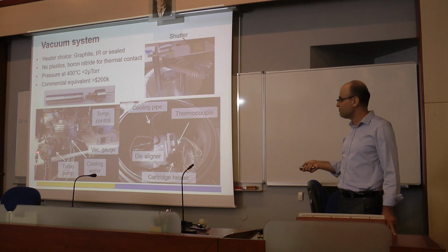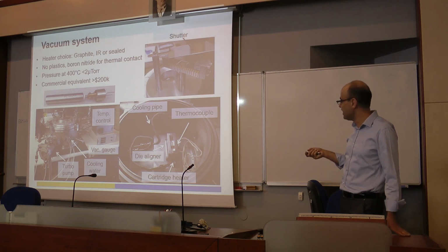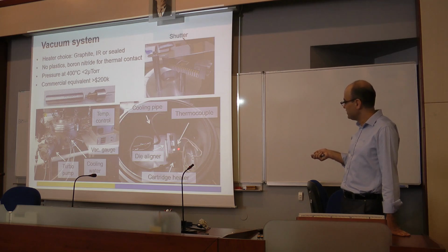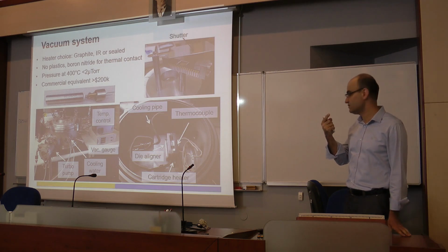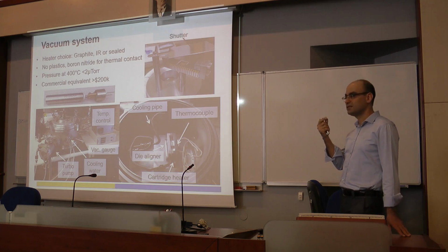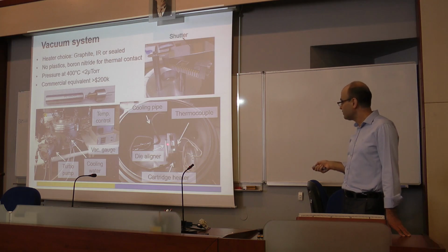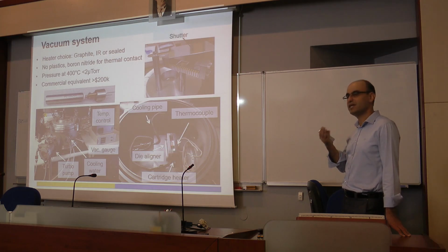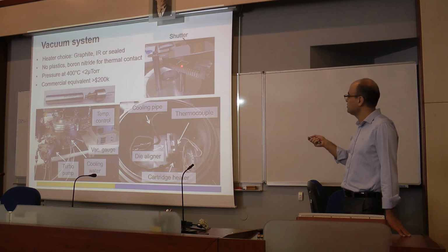So I have a vacuum chamber. It has pumps and I have my package here and I can move. This package sits in this aluminum mold upside down, and I have a heater here. First I put my lid, and then I heat the lid to a very high temperature. There's something called a getter, that's for that purpose. The getter will suppress your vacuum or keep your vacuum stable. Once the getter activation is done, I move my package upside down, and using a solder preform,